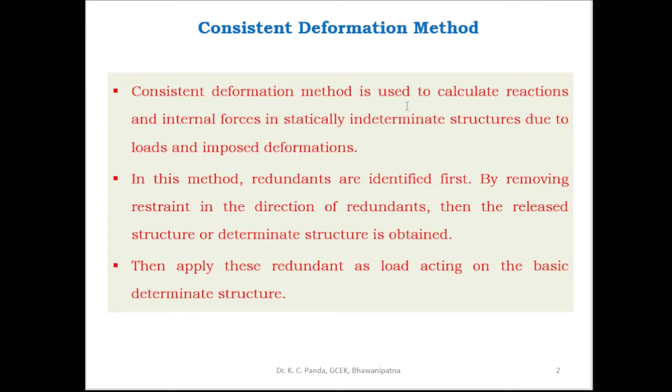Consistent deformation method is used to calculate reactions and internal forces in statically indeterminate structures due to loads and imposed deformations. In this method, the redundants are identified first by removing restraint in the direction of redundants. Then the released structure or determinate structure is obtained. Then apply these redundants as load acting on the basic determinate structure.